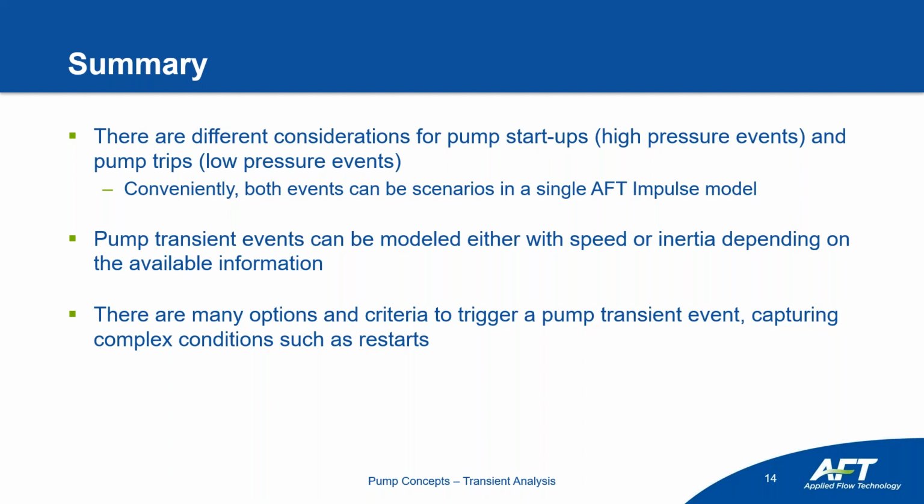And then you can also capture more complex conditions such as restarts. So you can trip the pump, it can entrain a bunch of air through a vacuum breaker, then you can see what happens when it ultimately restarts. Or if you have a more complex control system, again, you can use something like multi-condition events to check for all of those things all at the same time.